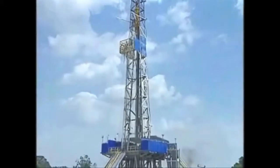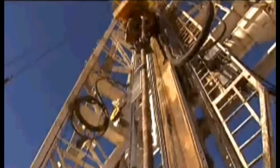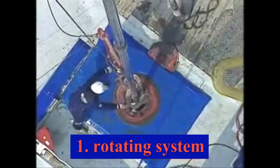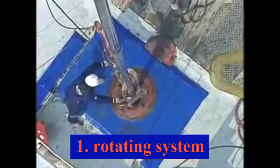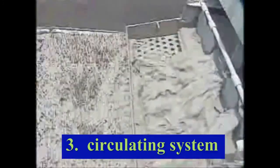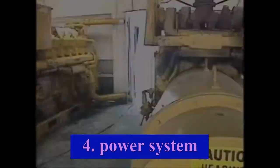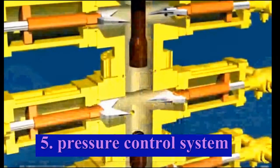Each drilling rig, no matter what its size or type, has one simple task, and that task is to connect the Earth's surface to an underground reservoir. To enable the rig to complete this task, there are 5 main components or systems. Each rig consists of 1. A rotating system, 2. A hoisting system, 3. A circulating system, 4. A power system, and 5. A pressure control system.